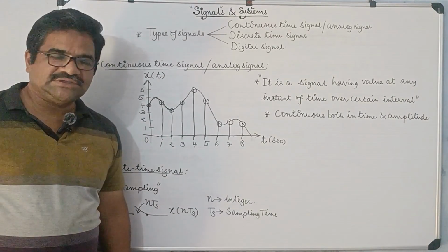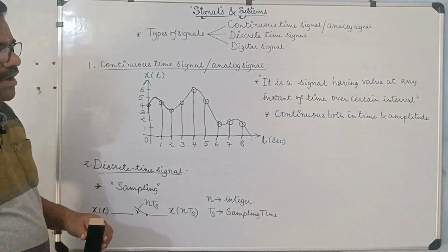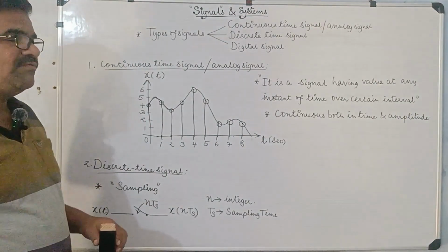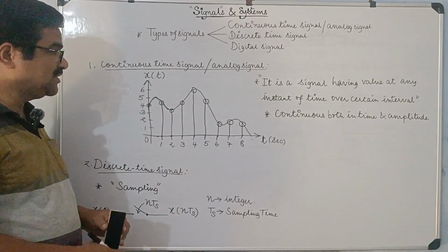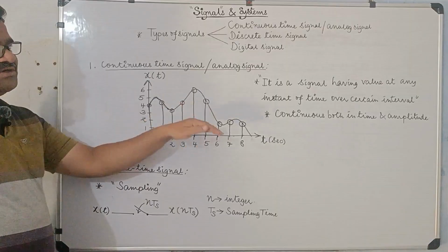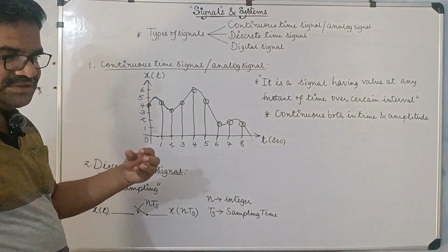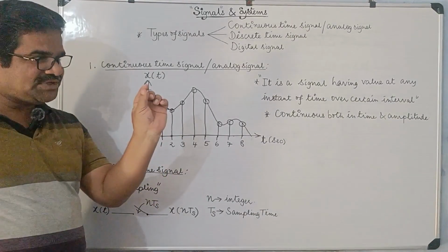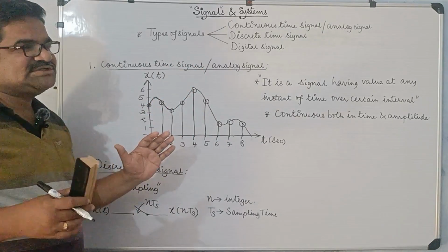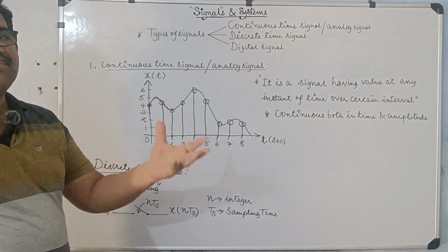It can be 2 seconds or 0.5 second or 0.25 seconds, and so on, depending upon what my sampling rate is. That is a separate topic. Depending upon the frequency of the signal, I have to change the sampling time. For high frequency signals, I should have more samples, so a very small sampling time, or the sampling rate should be high. For low frequency signals, my sampling time may be more, so I can have a lower sampling rate.